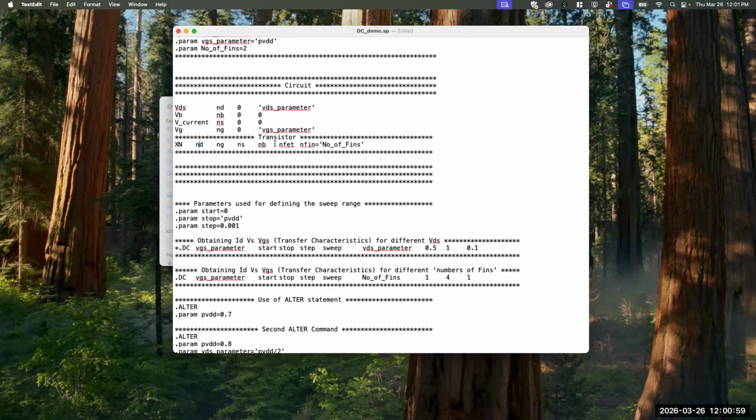Sometimes that's a dangerous situation because some models use parameters that the other model also uses, and they conflict with each other. I ran into situations like this, so you have to handle them accordingly. You have to update the model. But for example, based on how the PTM model is coded, if you include 20 nanometer model in the same code, you cannot do 14 nanometer model. You have to use a different code. These models cannot handle that. I don't think any model can handle it.